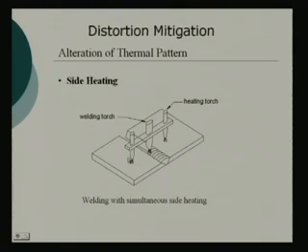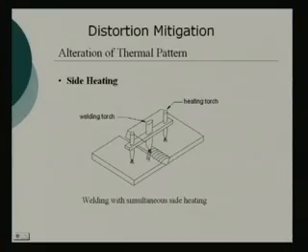If the temperature control of the heating torches is not proper, then it may damage the metallurgical property of the plate. What does that mean? That means the heat going in through the heating torches should be such that it does not raise the temperature above the recrystallization temperature. For normal strength steel, the temperature should be below 700 degrees centigrade, 723 degrees centigrade. For your high tensile steels, you should be even more careful, it should be below 650 degrees centigrade. So, that will depend on the